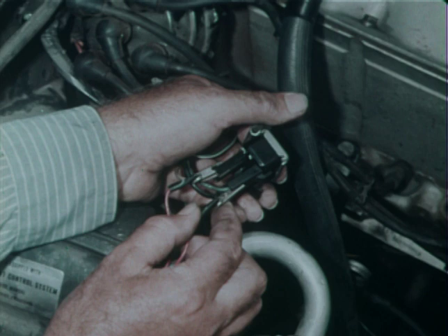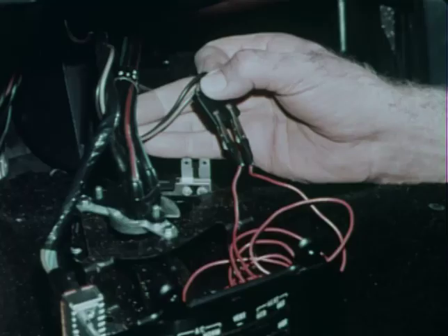To test the AC relay, he connects a jumper between the terminals of the two 16-gauge wires in the connector. This time, the clutch engages, indicating that the AC relay is malfunctioning. If the clutch had not engaged, the one remaining component he would have had to check would be the compressor clutch switch on the back of the control panel. The compressor clutch switch is tested by connecting a jumper across its terminals. If the clutch engages, the switch must be replaced.